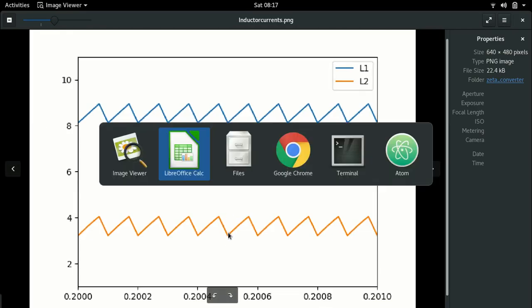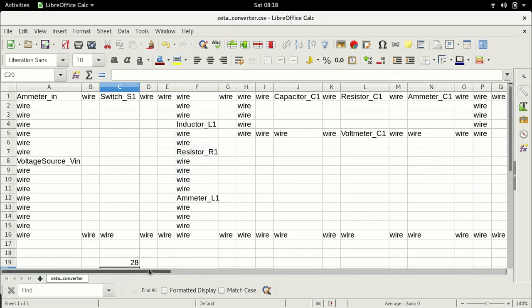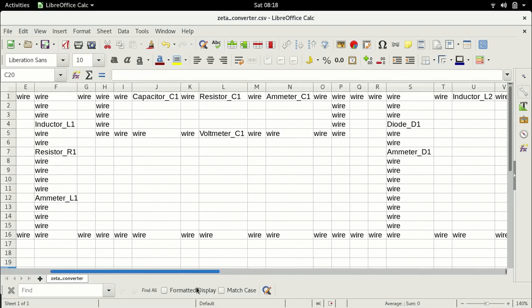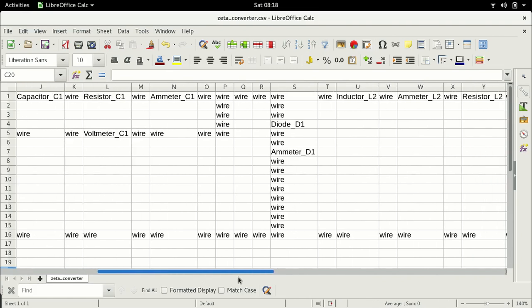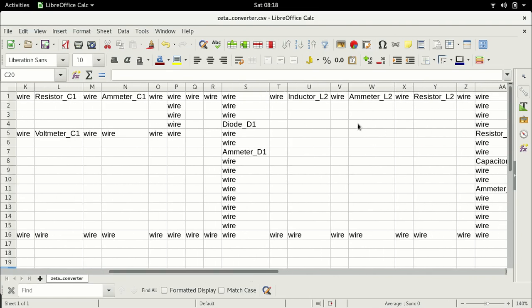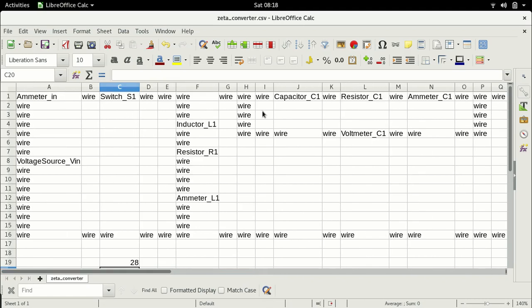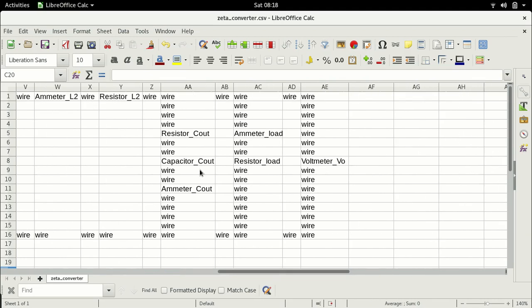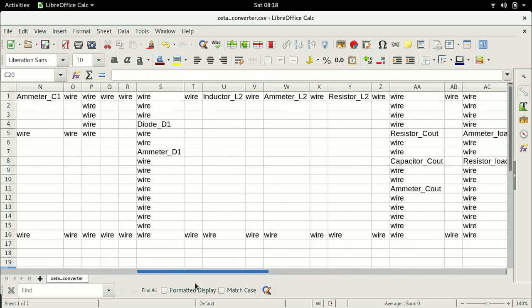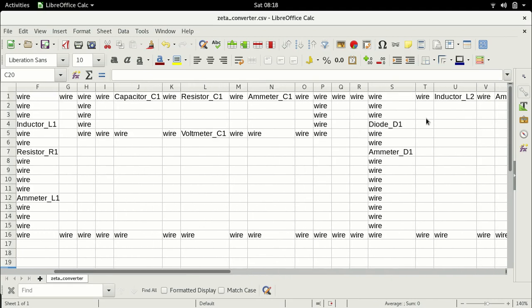The inductor L2 current, on the other hand, is largely a freewheel current, right? It receives energy from the input during the turn on state. So when the switch is turned on, it does receive energy. But it's important to understand that not only is the inductor receiving energy, the capacitor as well as the output capacitor are also receiving energy, right? So the inductor receiving energy is not exclusive.